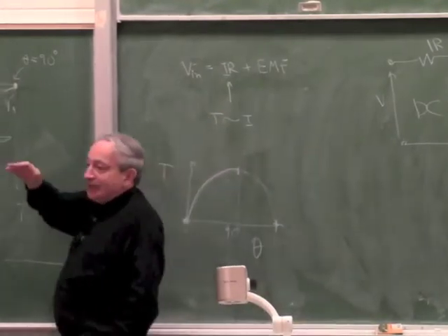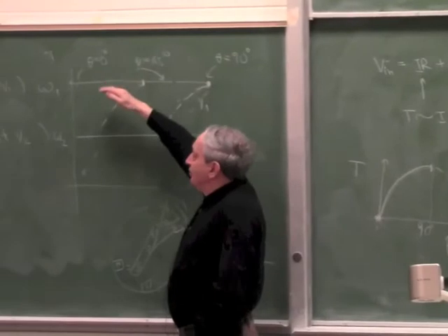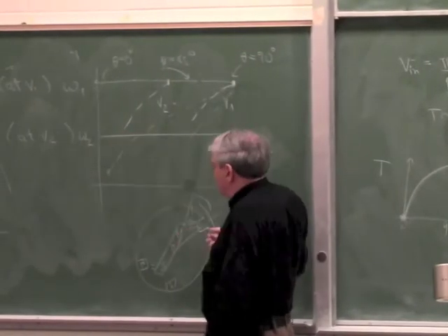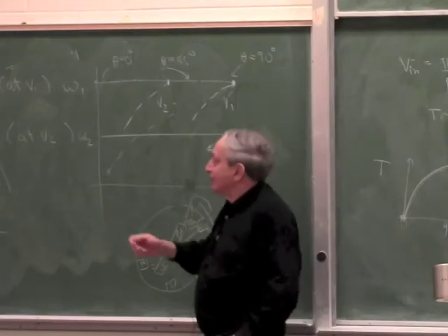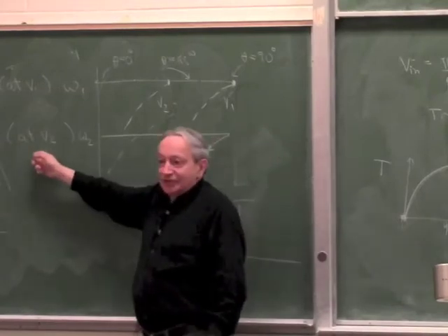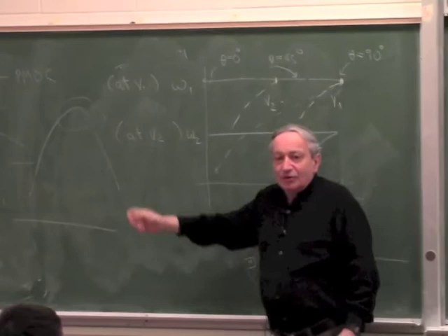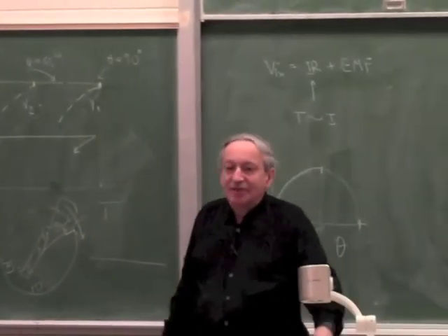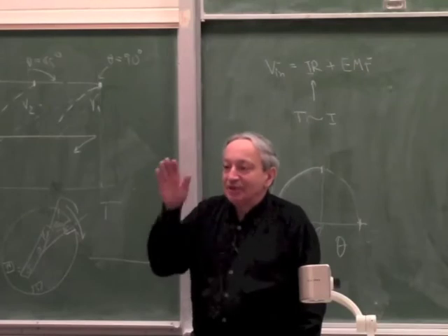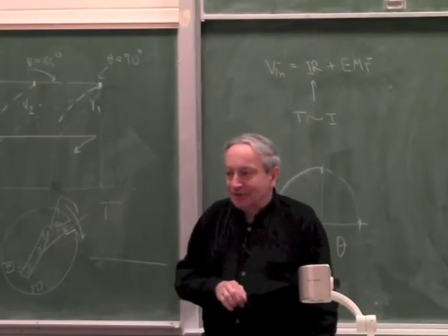But if I intentionally want to change the speed and I lower omega, there will be less back EMF. So for the same torque or the same current rating, I have to lower the voltage. Okay? All these variable frequency drives, like the one I showed you the demo with, when you change the frequencies, they automatically change the voltage. They are programmed for it.